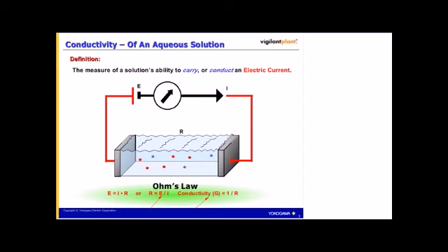An inductive sensor, on the other hand, has 2 toroidal coils, a driver and a receiver, sort of like a transformer, that are encapsulated within an inert material such as PEEK or Teflon, for example. And that material protects the coils from the process. And we'll talk about both of these sensors more as we move along.